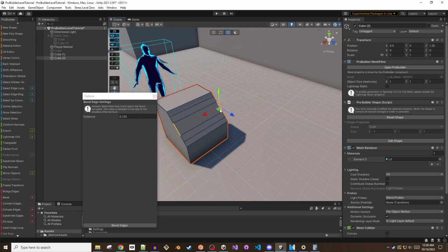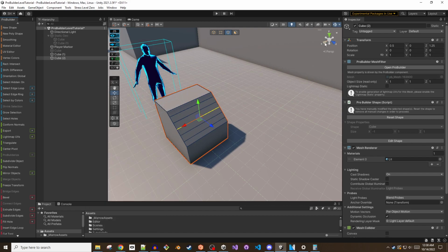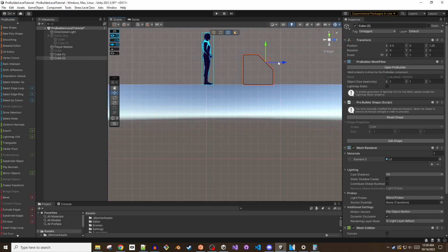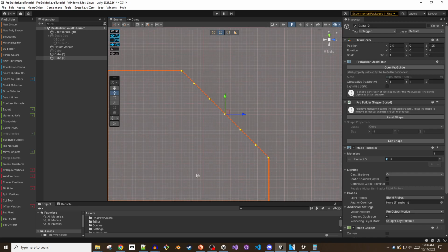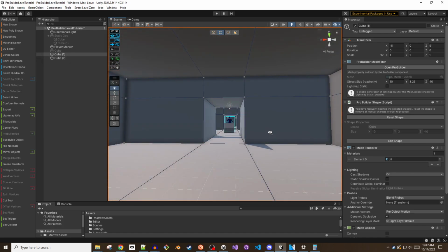If you wanted to simulate creating a rounded corner, you would have to diligently create additional edges and chamfers, making all the segments of the curve, and then manually arrange them into a smoothly rounded corner. Since Blender is free, I would highly recommend installing it and making these sorts of finer details there. Thankfully, it's easy enough to make these few detailed bits and then import them into your map. External meshes made by Blender and the geometry created by ProBuilder work quite well together.